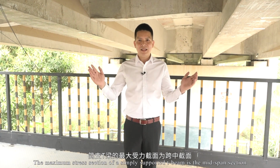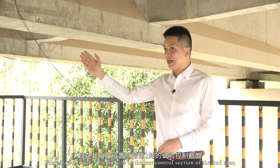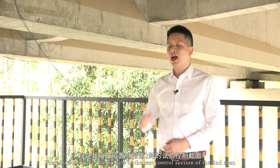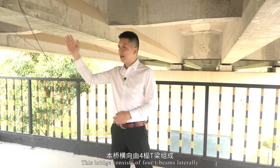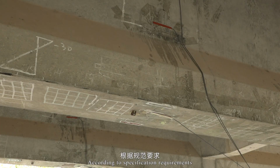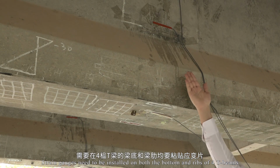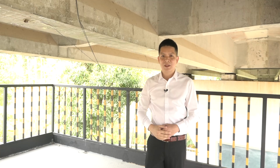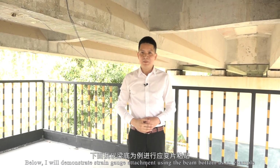The maximum stress section of a simply supported T-beam is the mid-span section. The position where I stand now is the test control section of the second span. This bridge consists of 4 T-beams laterally. According to specification requirements, strain gauges need to be installed on both the bottom and ribs of the 4 T-beams. Below, I will demonstrate strain gauge attachment using the beam bottom as an example.